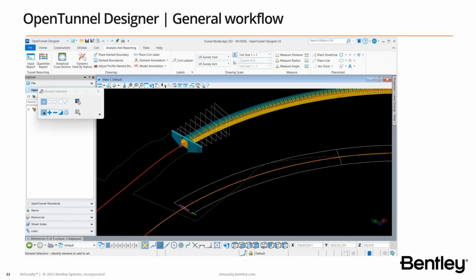No, there is a big difference between OpenRoads Designer and OpenTunnel. OpenRoads creates the objects as meshes, while OpenTunnel creates those objects as solids. Because we use this information later on, for instance, in ProStructures, where we need to add additional objects to our models, let's say concrete rebars or maybe steel ribs as the first support, our objects need to be created as solids.